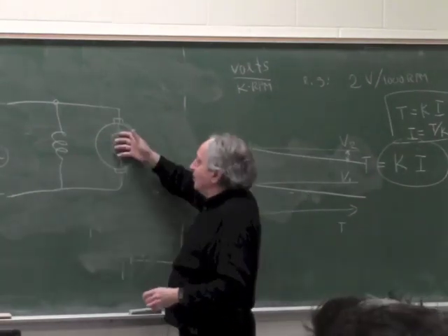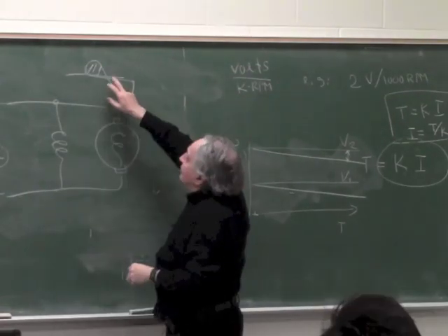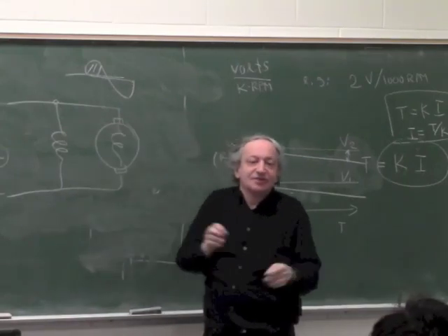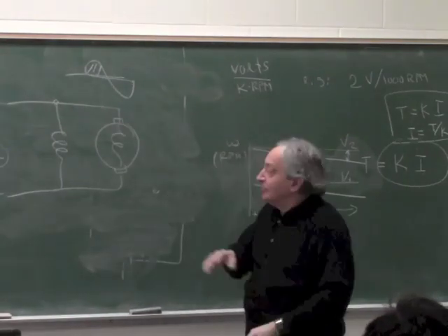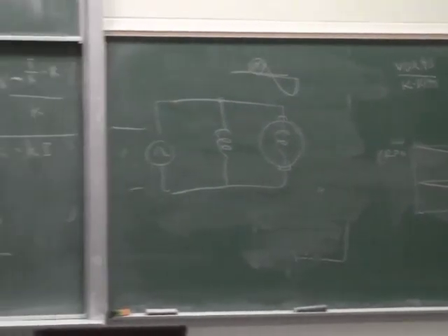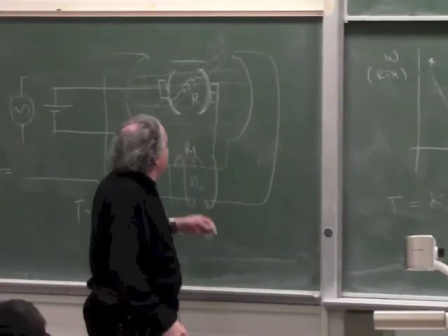When I have a sine wave and it goes to the negative half, both switch polarity, so the force stays the same direction. So in theory both this one can run on AC and this one can run on AC, but when you take apart power tools, it's always like this.